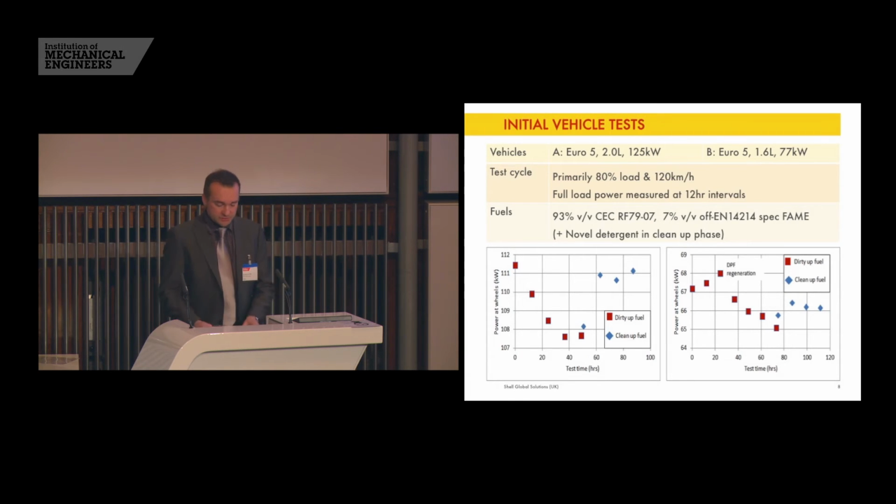And we used a fuel which was mainly comprised of the reference fuel used in the DW10B test, but with 7% volume of off-specification FAME to give some fouling propensity. And in clean-up phases, we added a novel detergent at a premium dose rate.